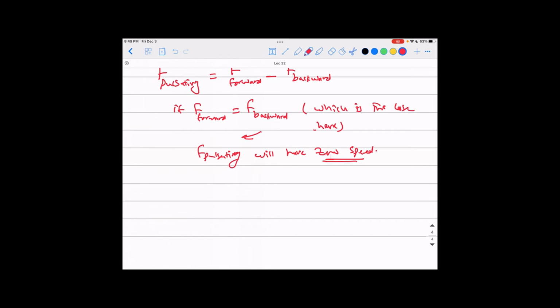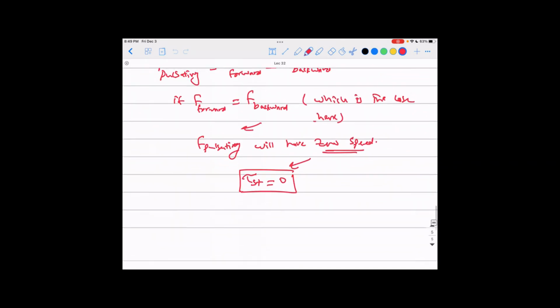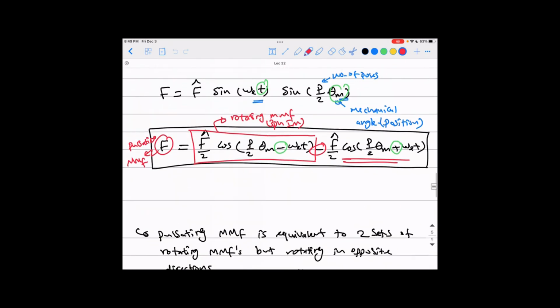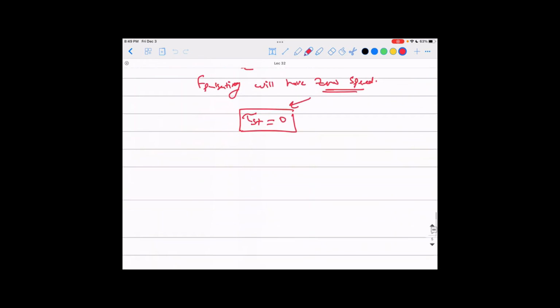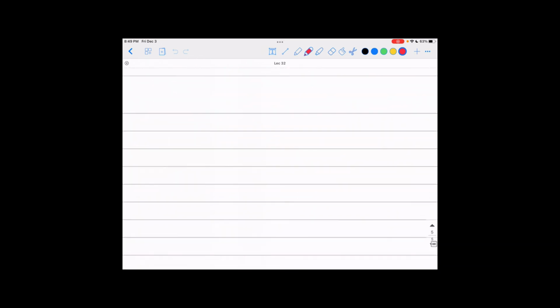Okay, guys? And that's why the starting torque of the motor will equal 0. The motor will not have any starting torque unless we do something to tackle this problem. So that's the whole point of having just a single-phase winding fed from a single-phase supply. It's a problem. The motor will not create torque, it will refuse to start.